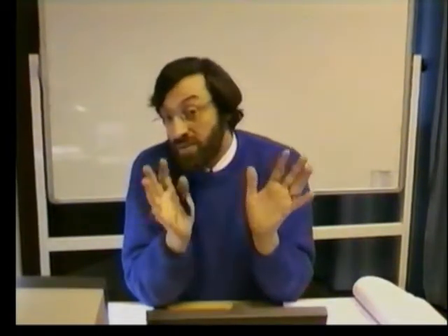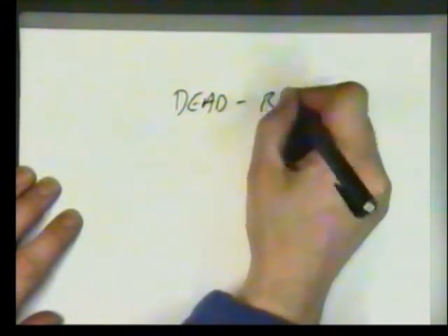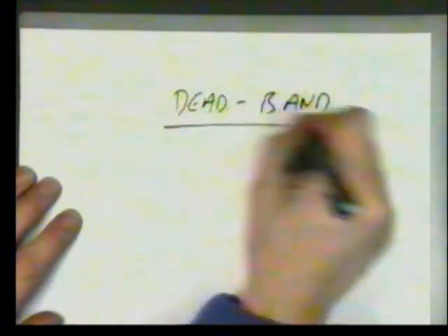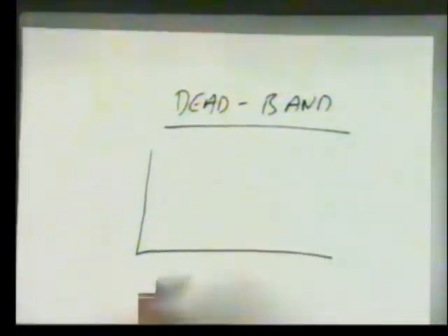Well, again, you can use hysteresis, but to not confuse the matters, I hope, I'm going to give it a different name. When we're in a situation where we can drive in both directions, I want to instead implement a thing called a deadband. Now, in fact, a deadband is negative hysteresis.